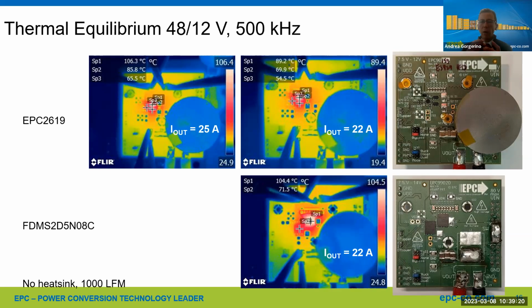So within one technology, if you start from a very small die or a very large die size, lower the RDS(on), and you shrink it, for a particular set of conditions you actually have an optimum size. And that means that you also have the lowest possible losses for the converter itself in that particular application.